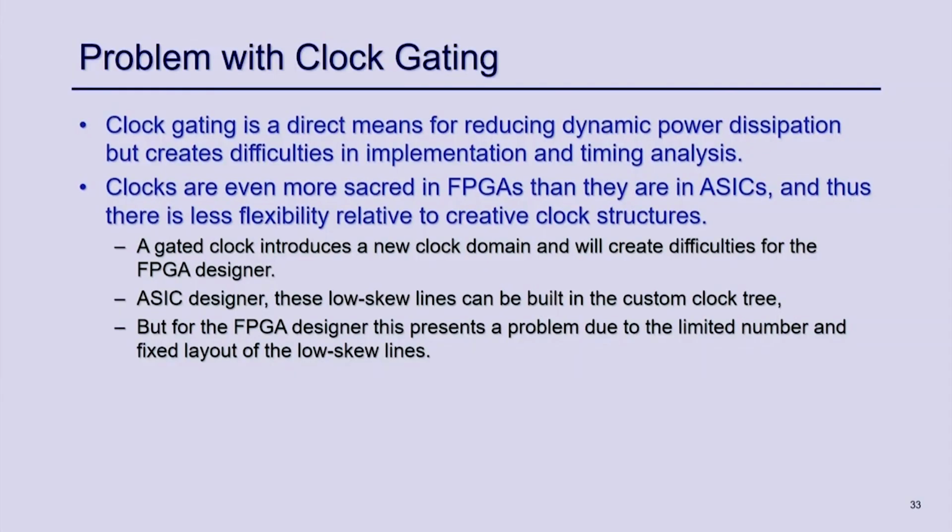Okay. Now, I will come back again to clock gating. We have talked about clock gating being a very useful approach to reduce the power of your design. But the problem with clock gating is that it creates a different clock domain, as I discussed earlier, and that is actually a problem for the timing analysis tool and implementation.